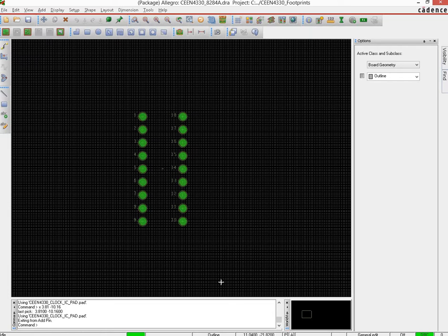Now, the first thing that you do after you are done placing the pads for a particular component is to create a box. That box will appear on your board as a silk screen, which is nothing but those white numberings that you see on the PCB, or the boxes which denote where the component is sitting. Those kinds of things are called silk screen. Later on in the video, where we discuss the various terminologies when it comes to PCB design, I'll show you what a silk screen is using an example.